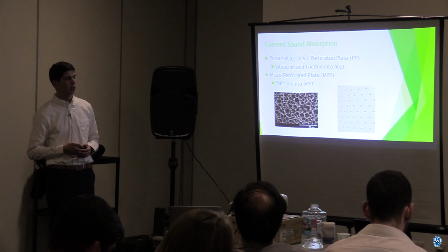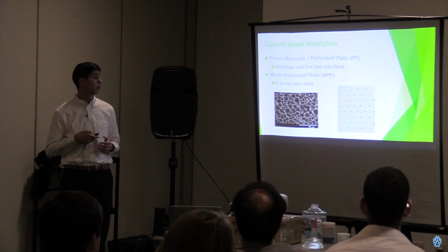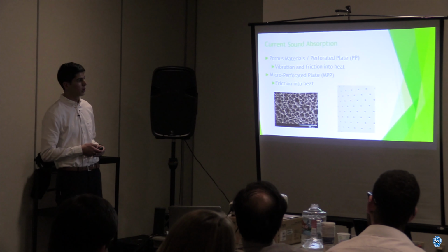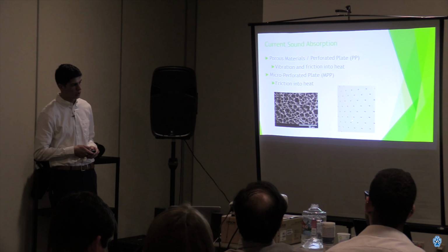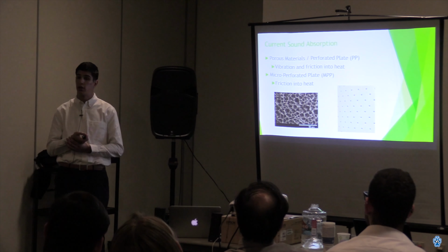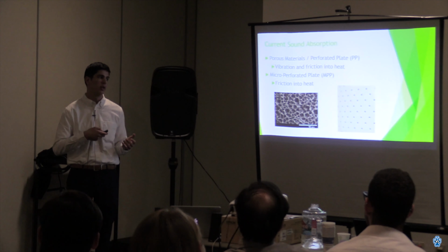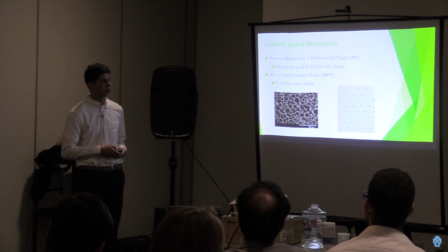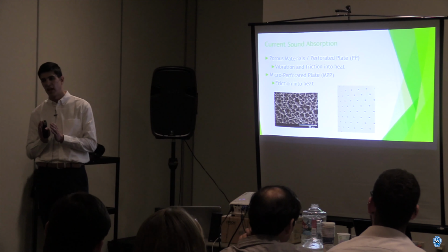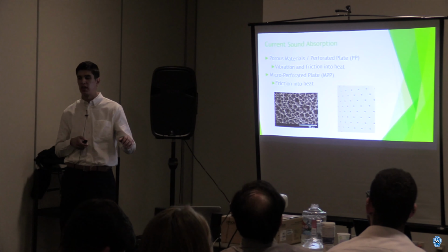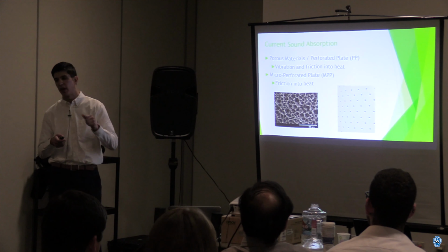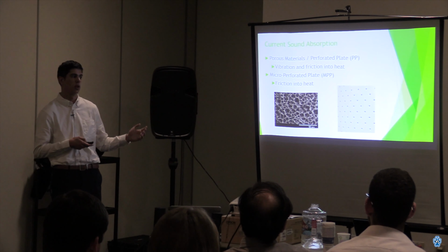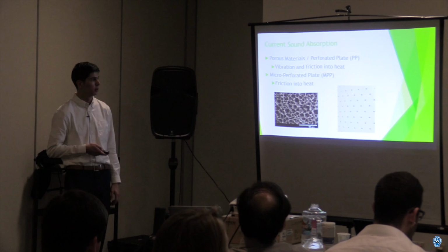So there's microperforated plates, and these are pressure absorbers. It depends on the pressure of the wave, not the velocity of the wave. How these work is when the sound goes into these holes right here, it interacts with the material, and there's friction. So the sound wave also loses energy to friction that way. The thing with the microperforated plates is there's a small gap behind there where the air gets pushed in, and I'll talk about this a little bit more in a sec, and then it comes back out. So it oscillates in between the holes, and it loses energy that way. So it has to do a lot with pressure instead of the velocity of the wave.